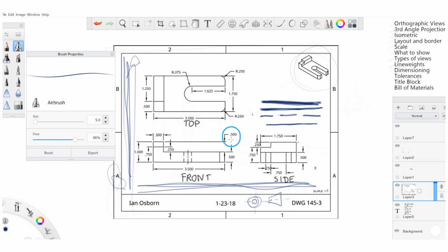Also we have 0.5 inch as a measurement from here to here, but that also isn't even very clear. This represents exactly the same thing by just process of elimination of 1 minus 0.5 is 0.5, so we can get rid of that as well and avoid all that confusion. We also have this length here from the front. You can see that all these orthographic views will and should always line up perfectly across the page, just like so. So we don't need to include that a second time.